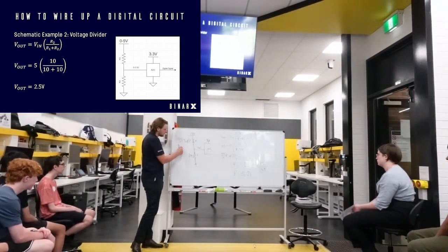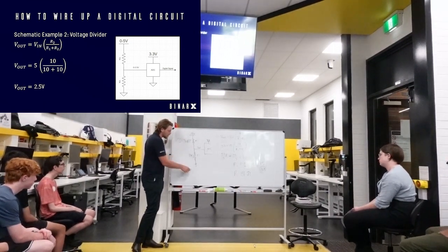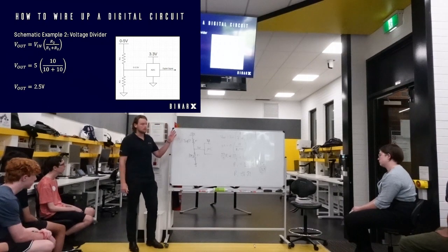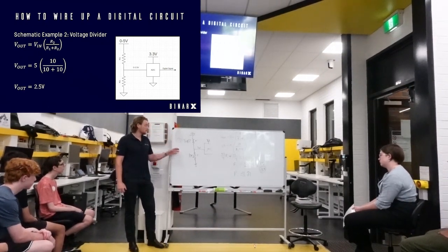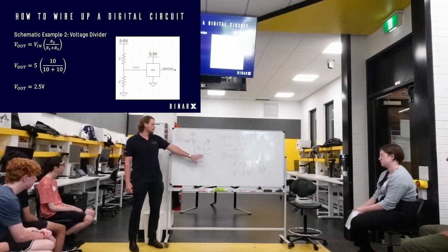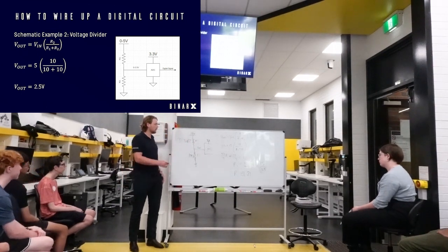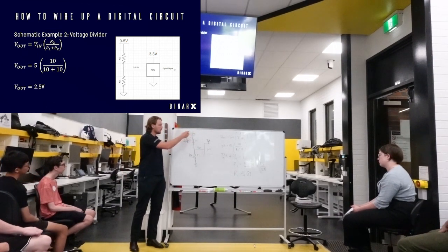if you think of this as our series resistance problem, 15 volts running through the total resistance of 31.8 and 10, so 41.8 kilo ohm resistance. Our current flow is going to be really low because of that. So our power usage is really low as well. Okay, so we're doing this purely as a reading to measure the voltage.